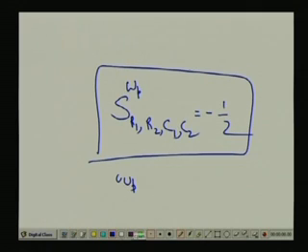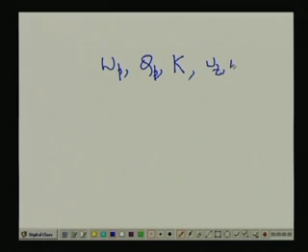Similarly, I can find the sensitivities of Q p, right. Typically, in most of the transfer functions which you have written, the filter parameters we are more interested in are omega p, sorry, let me take a new page, omega p, Q p, capital K, and if possible omega z and Q z.